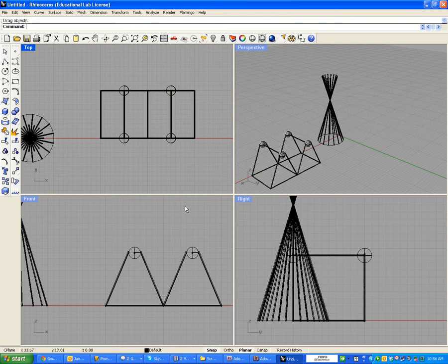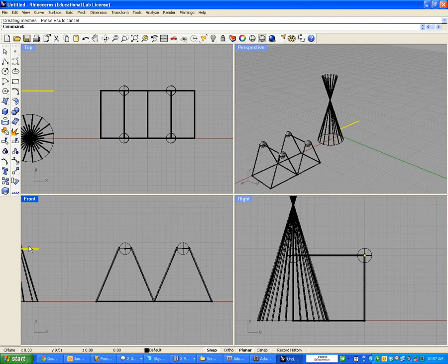Okay. Now in this case, I want to make another cylinder on the side, so I can put together these two structures. So I'm going to draw the cylinder right here. Let's make another cylinder. Oh, we can use one of these. Okay, let's draw it better. Let's draw the cylinder. So we're gonna go to the right view. The radius is gonna be 0.1, and the length is also going to be 10. Okay, so here we have it, and you just have to drag it to the right so we can put it in the center. Okay, so we have it right here.